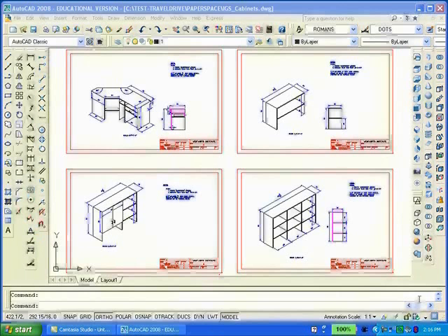If a 3D solid model is not required in a drawing, you can print the drawing in either model space or paper space. Some companies prefer not to use paper space and rely on model space exclusively. I was employed by such a company when I made the drawings that you are now viewing. These drawings include a desk, cabinet, and a couple of bookcases. Fractional units were used and the drawings were printed at a scale of 3/4 inch equals 1 foot.